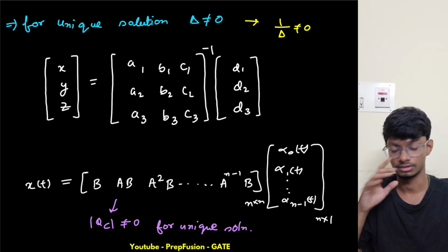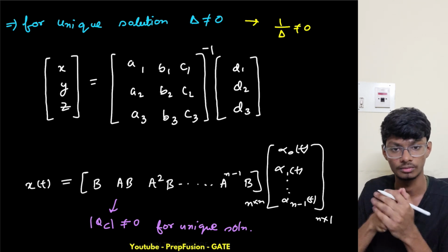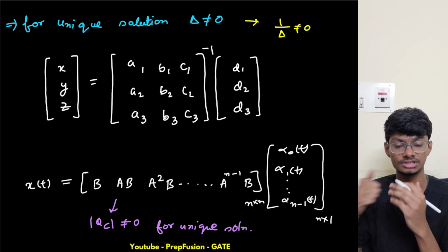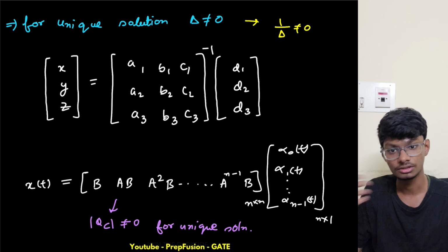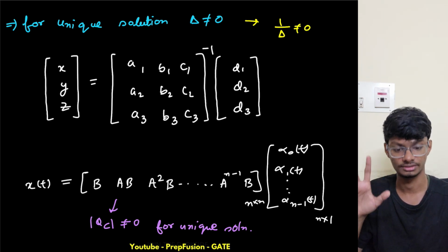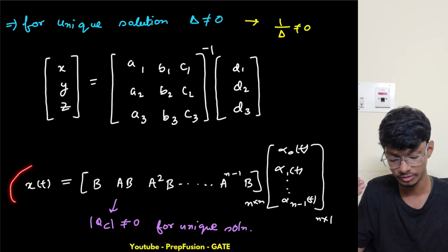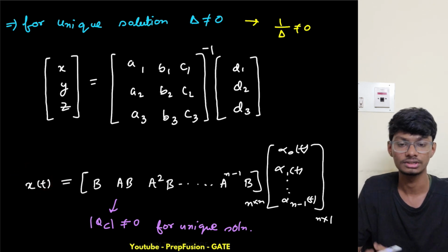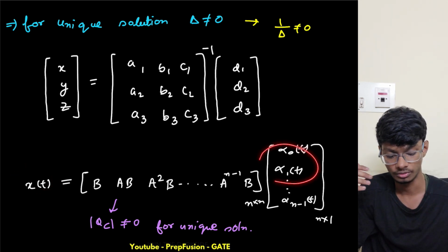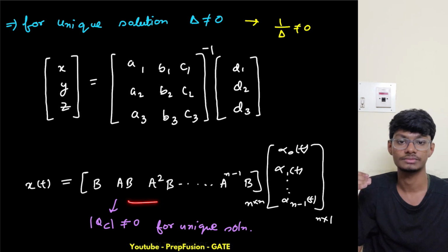The states variable won't be controllable, right? Our system won't be controllable. The state space representation isn't controllable. So that is the thing. If I am not able to get to my future state, a unique future state that I want to get through this control input, then that means the system is not controllable.